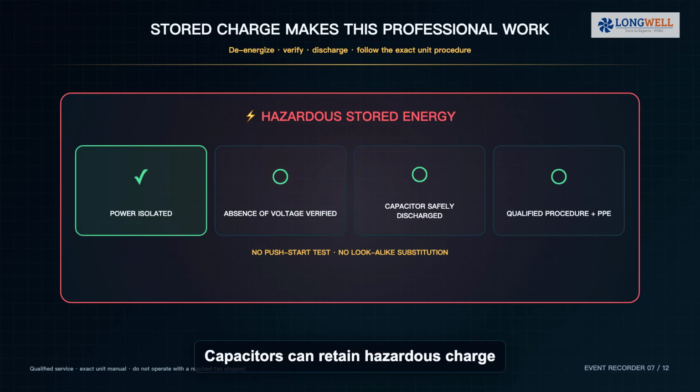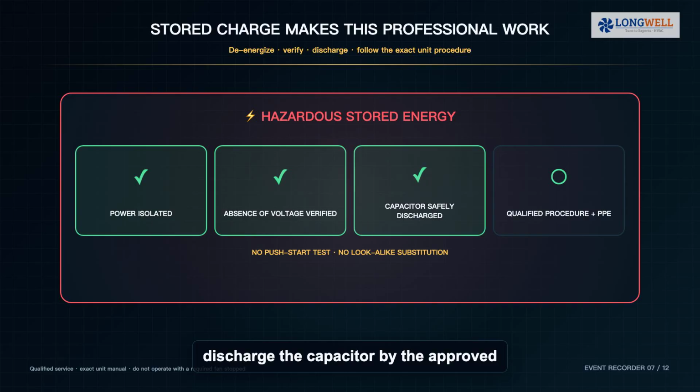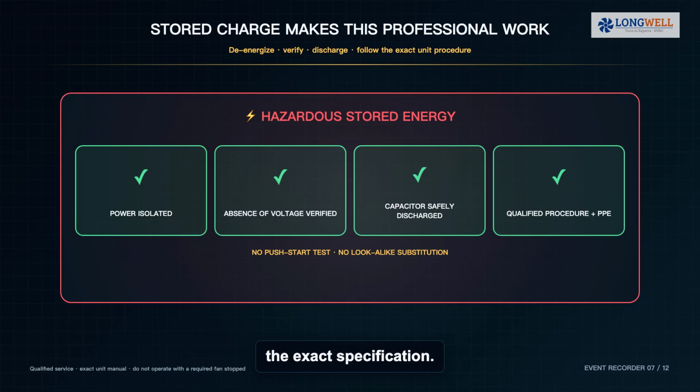Capacitors can retain hazardous charge after power is removed. Qualified technicians disconnect power, verify absence of voltage, discharge the capacitor by the approved method, isolate it as required and compare the measured capacitance with the exact specification. Never use a stick to push start a blade and never substitute a capacitor because its case looks similar.